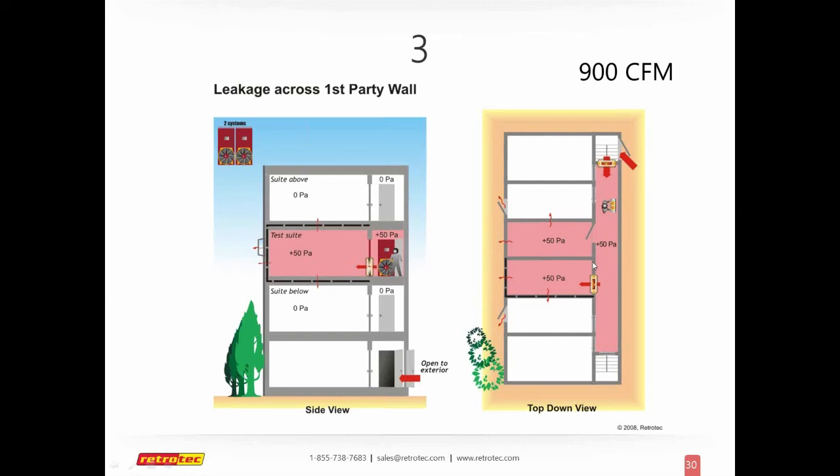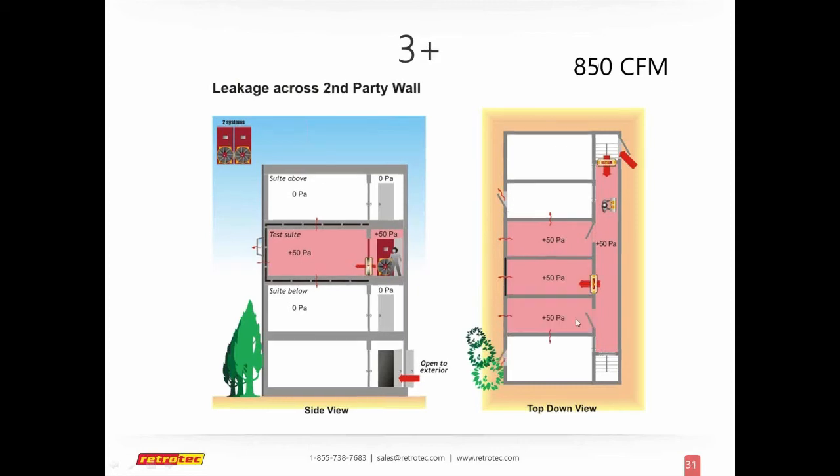And we'll do one more. I'm now going to open up the other section. So now I'm trying to pressurize all the sides around this unit, so I now understand the entire envelope. And it only went down 50. So I know that based upon this structure, this adjoining wall right here, adjacent wall, is where the majority of my leakage is. And I can now focus and do some more pressure diagnostics on this wall and determine what's going to happen. And I can retest to determine that I was successful in completing that.